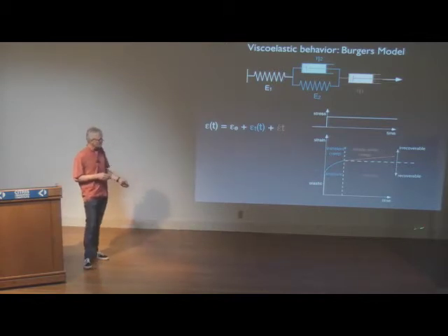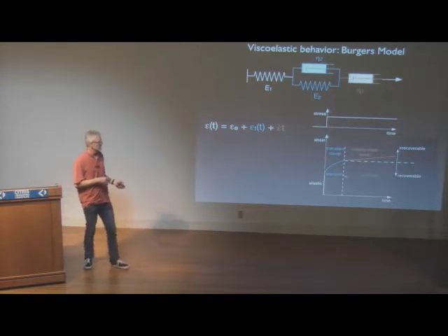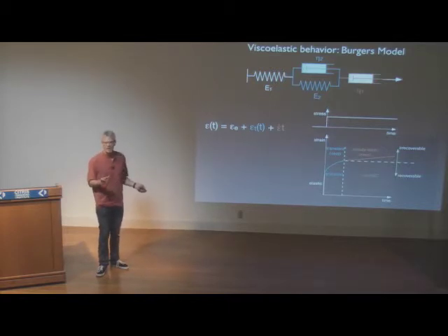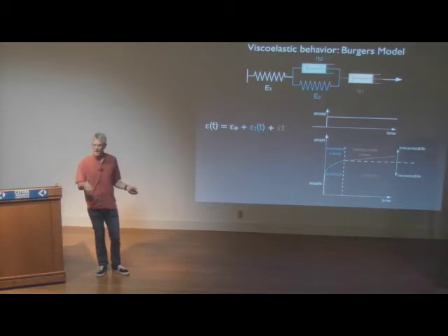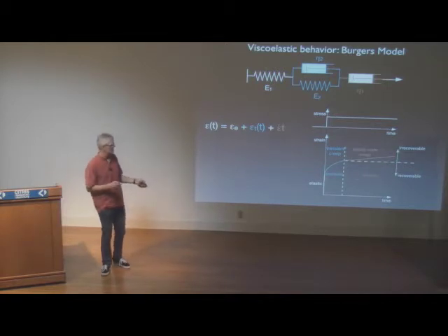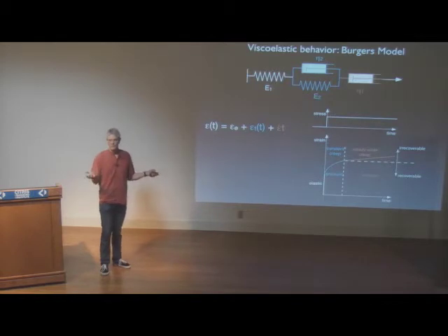So you can compose then a creep curve that looks like this. You have an elastic component, anelastic component, and then the steady state component. And recoverable versus irrecoverable: the elastic and the anelastic part, because there are springs involved, you can get that back. Whereas the deformation of this dashpot is permanent strain, you won't get that back. And that can be, here, this is relatively short time, that goes on by mantle convection.